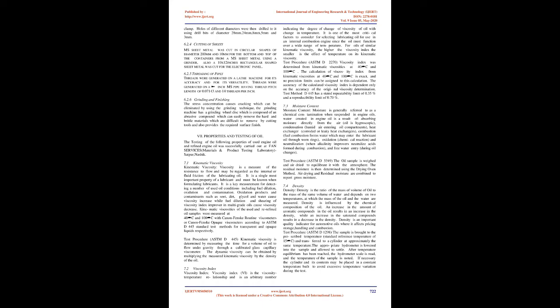6.2.6 Grinding and finishing. The stress concentration causes cracking, which can be eliminated by using the grinding technique. The grinding machine has a grinding wheel disc which is composed of an abrasive compound which can easily remove the hard and brittle materials which are difficult to remove by cutting tools, and also provides the required surface finish.